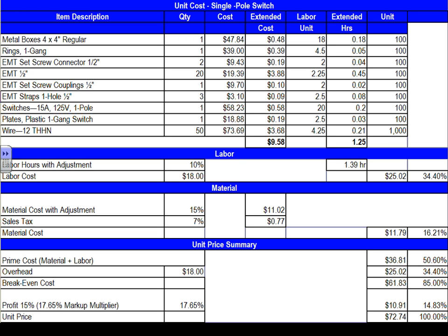Any comments, any questions? Very similar unit price, guys, ideas is the opening. A lot of people go count how many openings you have. An opening is a switch, a receptacle, a lighting fixture could be counted as an opening. Wherever you either control the circuit or take power out of the system, that's going to be your opening. So that could be one opening here. The switch is going to be another opening. A receptacle is going to be a third opening. So that's typical, similar to an opening, guys.